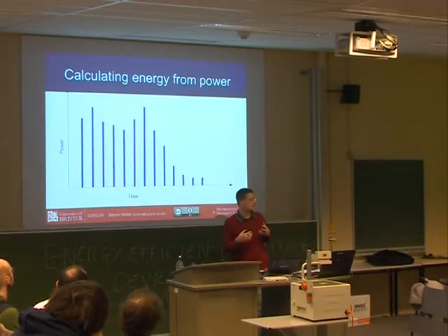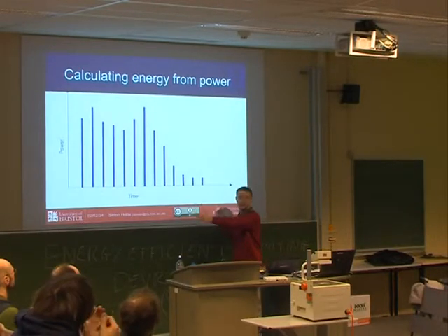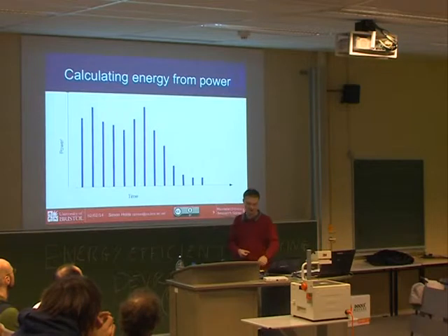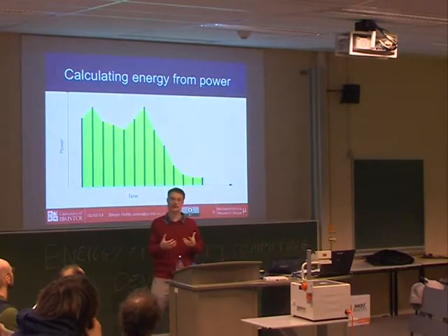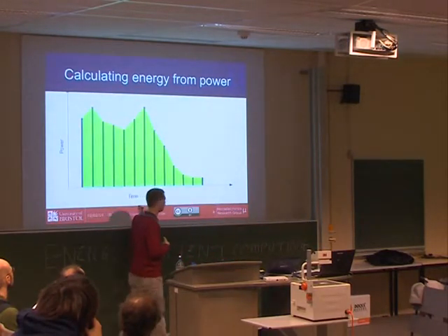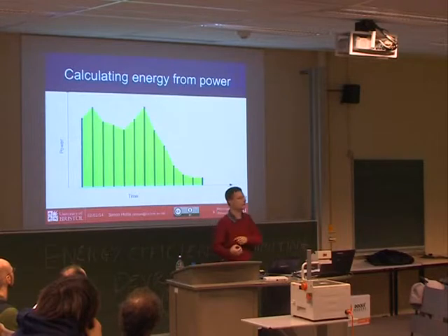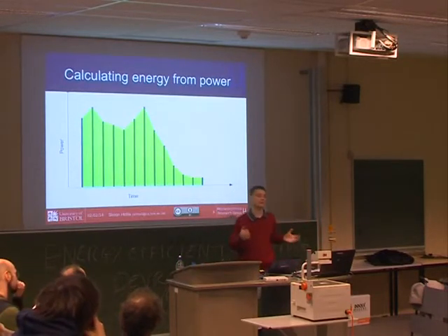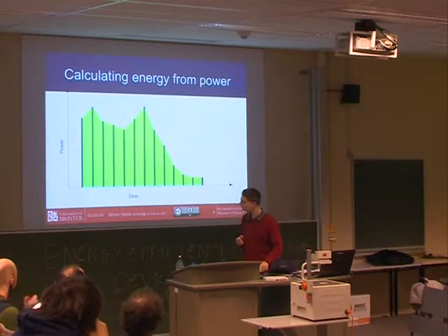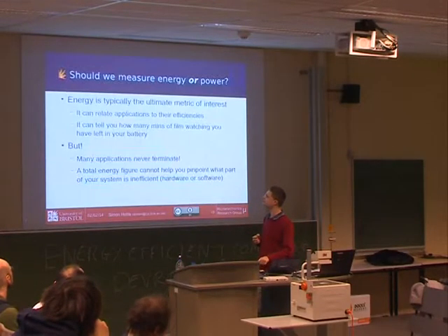You can convert that easily into energy. If you have that set of measurements, you've got a set of power measurements through time, and you can say lots of things about the power consumption of the device. You can also perform the integration process, which just measures the area under the curve, and now you have energy. The area under the curve is the energy, from the measurements of power. So you get both at once. You just measure the power, and you have everything you need for energy, and more.